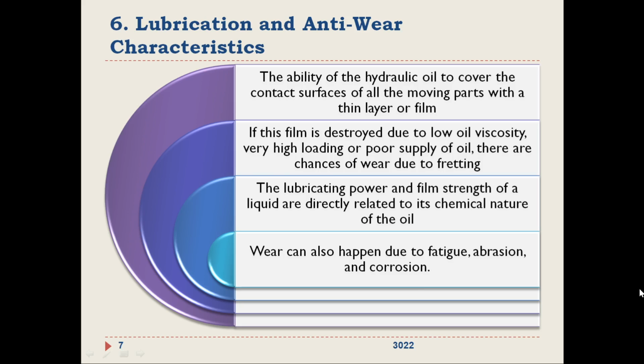If the thin film is destroyed, what will happen? Suppose the viscosity is low, so the oil will flow quickly, and the oil film will not form. With very high loading or poor supply of oil, if the supply is not adequate, there are chances of wear due to fretting.